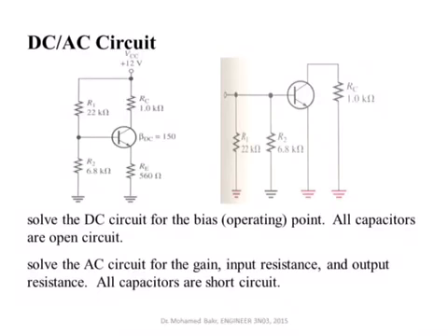So these are the two circuits we have to analyze. The first one here is a purely DC circuit. We removed all the capacitors, we consider them open circuit. We have to solve for the operating point: I_C, VCE, I_B. You have to solve for the currents and voltages everywhere.